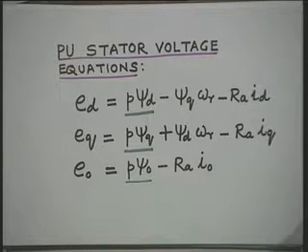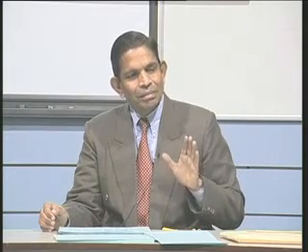Then the question arises whether this is a realistic assumption, whether the results which we will get by ignoring these terms will be acceptable. People have done a lot of research on this, and after performing detailed studies, the conclusions drawn are that yes, we can ignore these terms, that is, the stator circuit transients can be neglected.